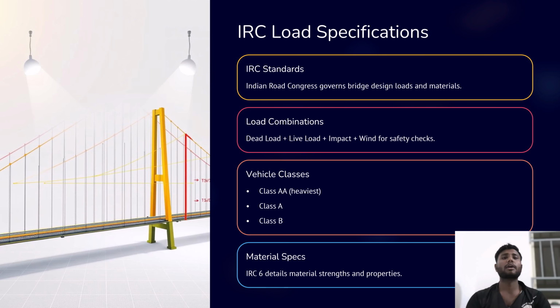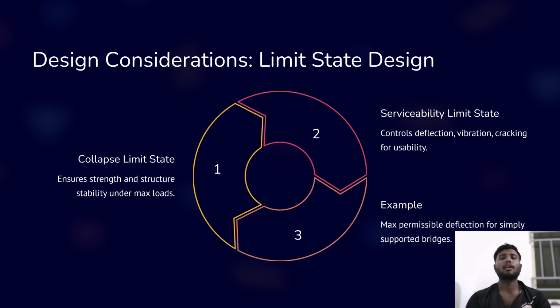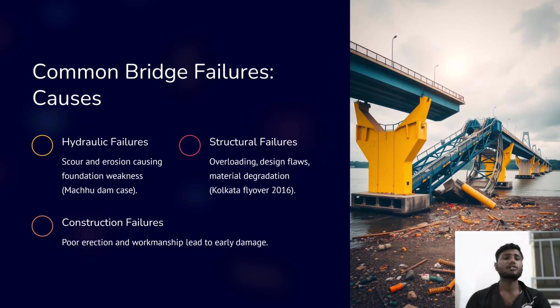So moving ahead, design considerations: limit state design. In the collapse limit state, we ensure the strength and structural stability under the maximum load. In the serviceability limit state, we control deflection, vibration, and cracking for usability. And the next is the maximum permissible deflection for simply supported bridges.